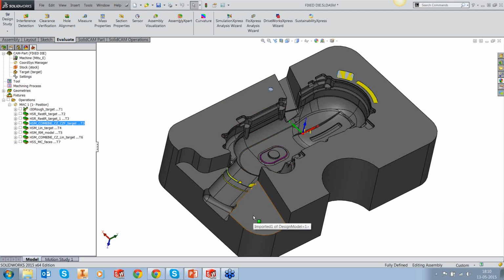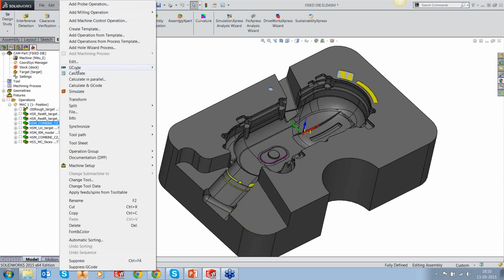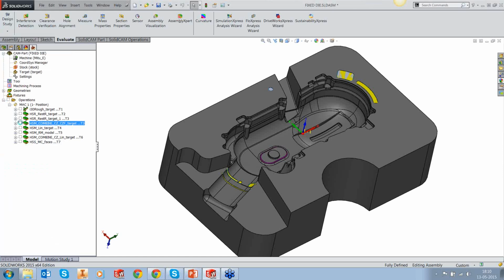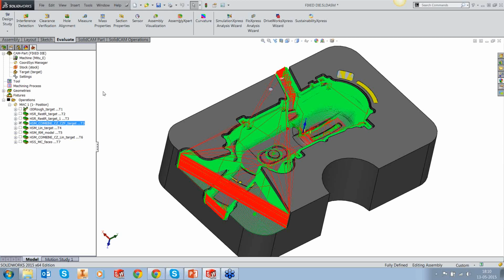Or if it has to cut horizontal, then it has to be absolutely horizontal. So we have a toolpath generated using a combination of constant Z and horizontal only. If you look at the toolpath, it looks something like that,